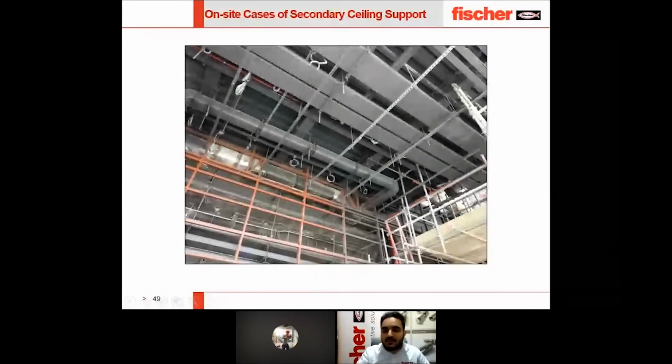The capacity for your system depends on the channel and the channel size. We have a Fischer catalog. You can go to the website and download it, and you can see the capacity for each channel. There are many capacities for each size of the channel, and the anchor capacity. We have to consider the anchor capacity, the flange, the bracket capacity, and also the channel capacity. We make a full study for the consultant, and for you. We check each bolt and part in this system, and we ensure that it is very safe with the safety factor.